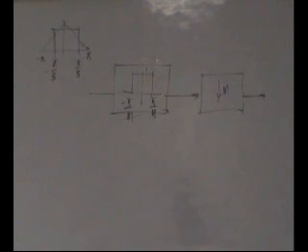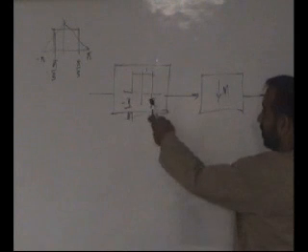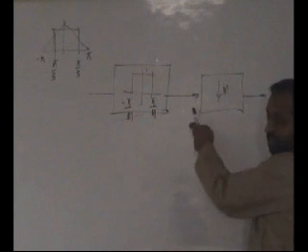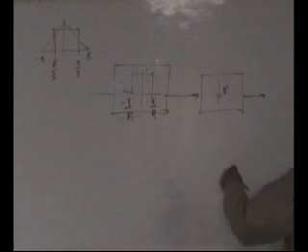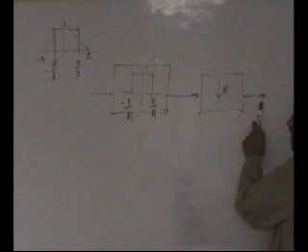That you are actually computing samples which ultimately you are going to throw away. Let's say M is 36, so you compute 36 samples, then only keep one out of those 36, throw away 35. The obvious question is, why should I compute what I am going to throw away? I should not compute that. This is the real motivation. Why should I compute something which ultimately I am going to throw away?